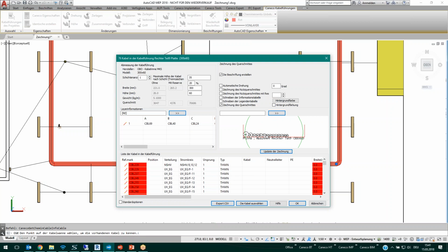And I can see that Patricia did a good job in Revit because she has the size as 300. What is needed with the reserve at 20% is just 265. It's enough. When I want to have, for example, 50%, you can see here which size is necessary: 331. So your 300 is not enough.